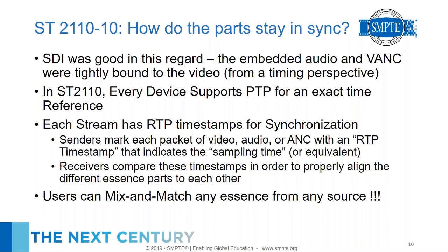Many devices also support 125 microsecond packet time, and there are applications like in-ear monitoring and other things where it's actually quite important to use the shorter packet times. But yes, if you use 1 millisecond packet time, then you have at least 1 millisecond of delay because you've basically waited a millisecond to gather up 48 samples in the case of 48 kilohertz audio to put together in one packet.